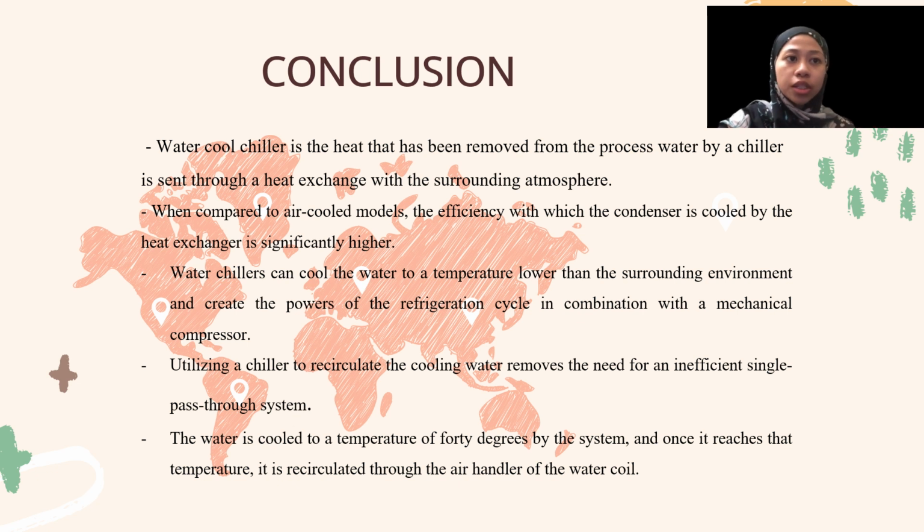Also, water chillers can cool the water to a temperature lower than the surrounding environment, using the power of the refrigerant cycle in combination with a mechanical compressor. Utilizing a chiller to recirculate the cooling water removes the need for an inefficient single pass through the system.